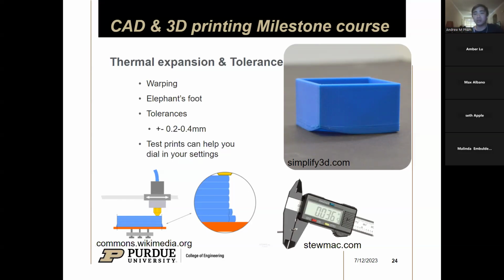This is partially because of the process of the manufacturing. Because you're heating up the material and cooling it down, it's subject to thermal expansion, right? So it'll kind of grow and shrink depending on how warm it is. So when you print it, it might print oversized, but then once it cools down, it might shrink. And part of that could cause your design to warp.